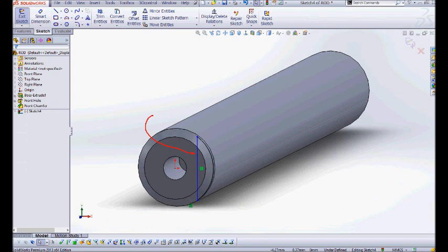Now, this is the part that I need you to watch. Question about this: when you're getting ready to do a feature in the drawing, what about the orientation on the XY axis? Should we be considering it now, because it would have any bearing later on? Well, I've got a vertical constraint on this line, and it's right there on the y-axis. When we place the rod in the assembly, we'll be able to orient it however we want the keyhole to be oriented.